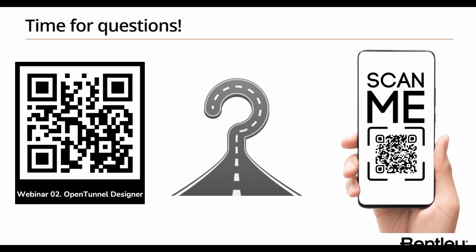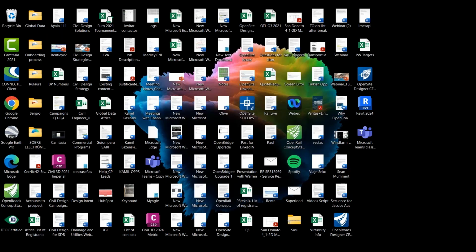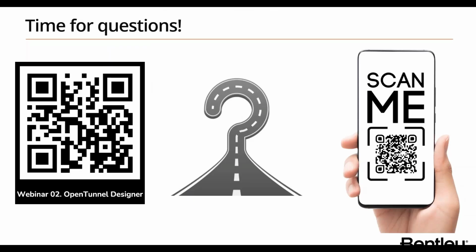I can place the rock bolts on all the sections, and I can place only, let's say, the fiberglass for shotcrete on other sections. So I can use the rock bolts on top, but at the bottom, maybe using the same rock bolts command, I would like to create some micro piles or piles. So again, this is possible.